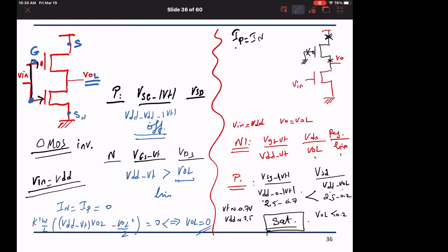So the CMOS inverter works in a way that when I want to pull up or pull down the output, one of the devices will be off, allowing the other device to force the output fully to 0 or to VDD. There is no contention from the other device. Okay, this is the basics of the CMOS inverter. Clear? Does anyone have a question on this?